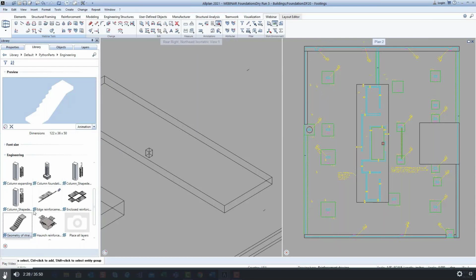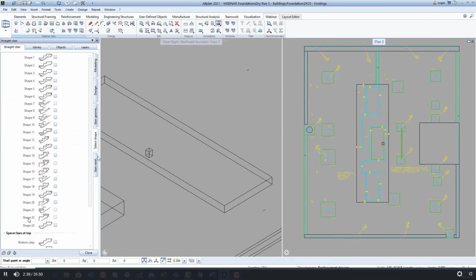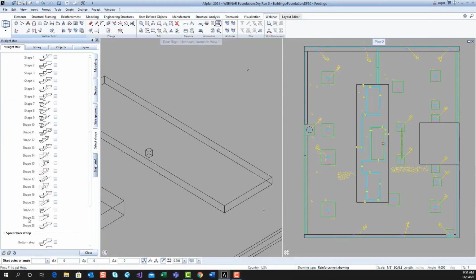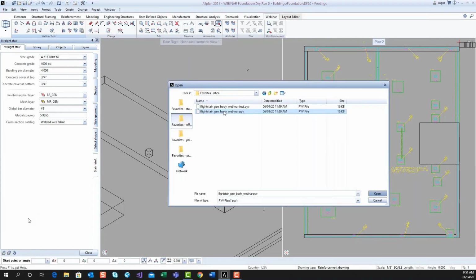And you're going to see that when I put in this step, or what we're going to call a step footing, I'm going to load in some predefined values that I've already set up. It's a couple 15-inch steps on this. It's got a slope already predefined. And once I've loaded in my values, I'm going to place it in my drawing view.